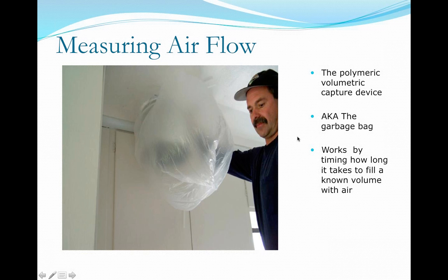Again, the basic principle of operation, it works by timing how long it takes to fill a known volume with air. The things you have to be careful about is the definition of fill, the ability to take the timing, and also not to restrict the airflow. Again, like we talked about the smothering effect, if this introduces a back pressure, then you're no longer measuring the airflow out of the grill, you're just measuring a reaction to the back pressure.